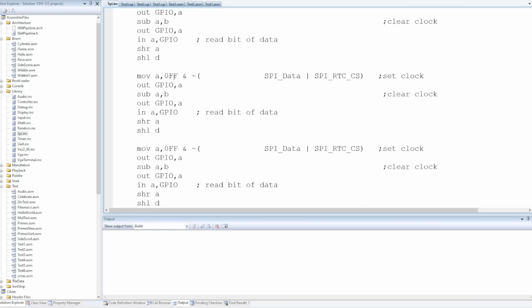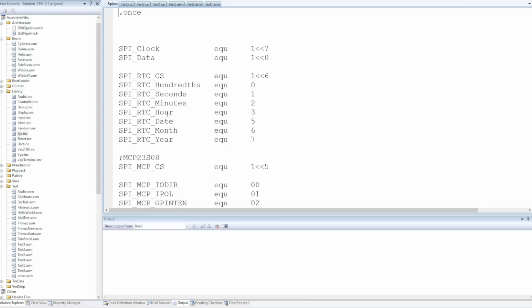Now here I'm setting A with a combination of bits inverted, and that's because the way chip selects work are a little bit of an annoyance. These are actually active low lines, which means as I use additional lines for each new device, I have to make sure that that line remains high all the time I'm not using it. So I kind of started off by solving that problem by setting every bit on the output and then unsetting them as I was using them. But that's actually going to be a bit of annoyance as we go, because we've got a total of 8 bits, so we're capped to 8 devices minus however many additional control lines we need. So I think this is the first place that would benefit from a small amount of extra circuitry to help us both avoid contention of multiple devices selected, but also expand the number of devices we could theoretically attach.